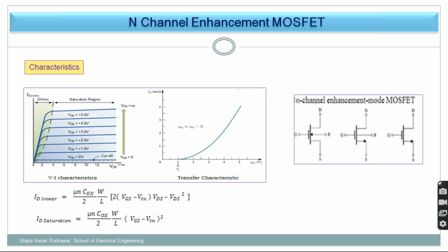It should work in the linear region. So whenever you have to use the transistor as an amplifier, it should be in the linear region. In the linear region, your current increases with increasing voltage. So hope this basic is also clear. For a switch, it should work in the cutoff and saturation regions, and for an amplifier circuit, it should work in the linear region.